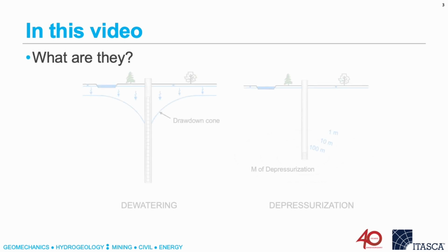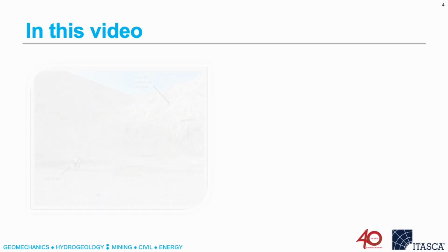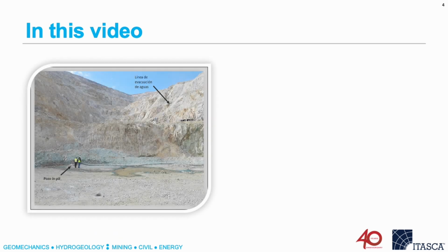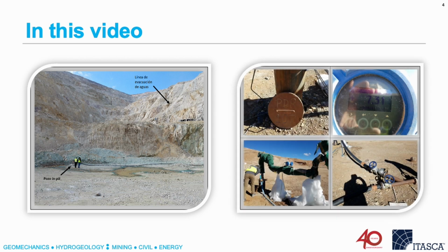Pumping wells are vertical boreholes that can have the purpose of depressurizing or draining a certain rock mass. To determine their potential effectiveness, it is recommended to carry out a pilot pumping test beforehand to understand how the hydrogeologic system reacts to the extraction of groundwater.